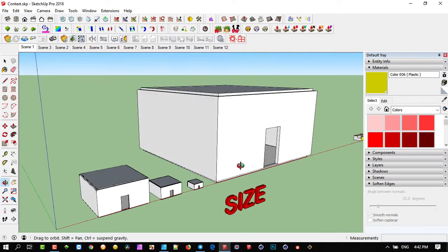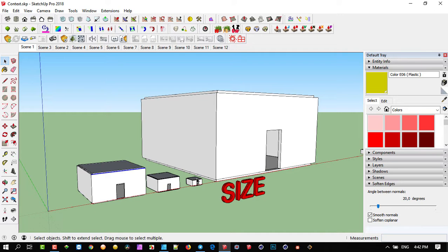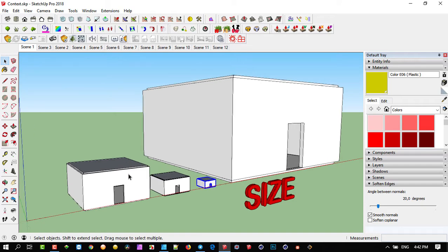So often when I started designing in SketchUp, I would just draw a model and not worry about size. Cinema 4D is about the same thing. You just pull out a block and you start to model, and you don't worry about the actual dimensions. But now when you're coming to rendering, the renderers today depend on physical size. So if you're creating a room, let's say we're looking at these three rooms. If you're creating a room that small size or this size or this size, and you're using the same lights inside of it, they're going to react totally differently.